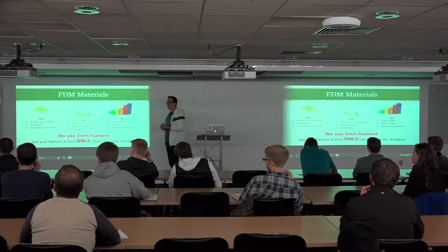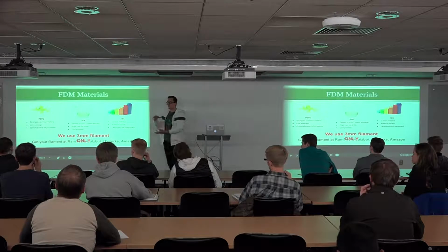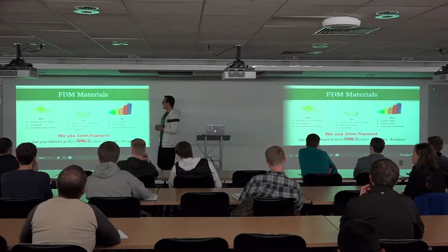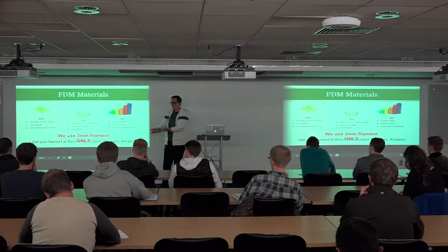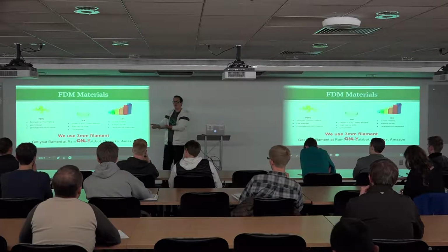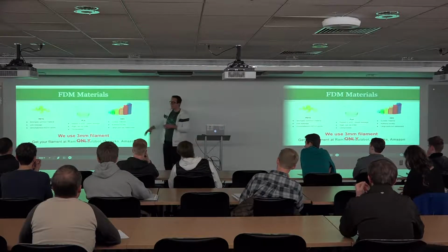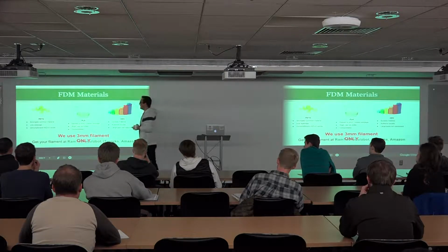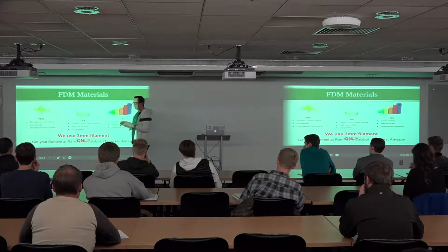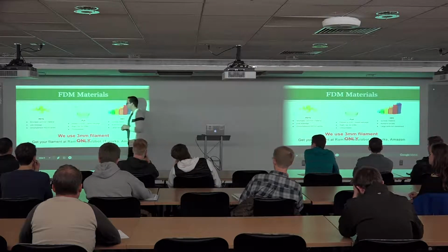90? Yeah, just because of the detail we wanted and the size it took, about 90 hours print time. So an ABS print probably wouldn't survive that long because eventually it starts to warp up on the bottom and it pulls up off the bed. So ABS is great for Legos and small things like that. Actually, Legos are made out of ABS, and we've printed our own. But for larger parts, ABS is not quite as good as PETG.